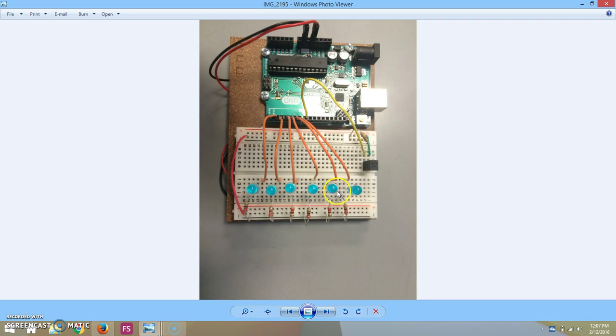Here on the right side we have 6 LEDs connected, with the 220 ohm resistors grounding the LEDs, and the wires connecting to the LEDs to record the output of each interval. And the tilt switch, with the up direction this way. Then here's the 10K resistor connecting to the tilt switch with the wires in between to read the input of the tilt. And the small green wire back here is for powering the tilt switch.